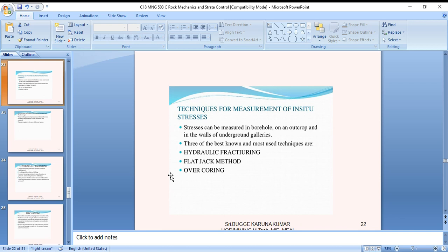If the core is displaced in either direction from the center position, the unbalanced voltage distribution in the secondary is proportional to the core displacement. The differential voltage in the secondary is independent of the frequency in the specified operating frequency range, depending on the voltage of the linear variable differential transformer, a desirable quality.